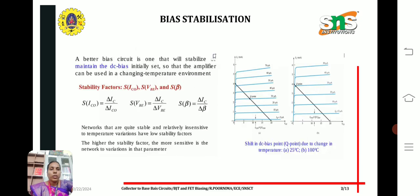So you go for bias stabilization methods, which depend on the stability factor. A better bias circuit will stabilize the collector current and maintain the DC bias. The stability factors are given as the ratio of collector current to collector saturation current, the ratio of collector current to base emitter voltage, and the ratio of collector current to beta. The networks that are stable and relatively insensitive to temperature variations have low stability factors. A higher stability factor means it is more sensitive to variation of parameters.